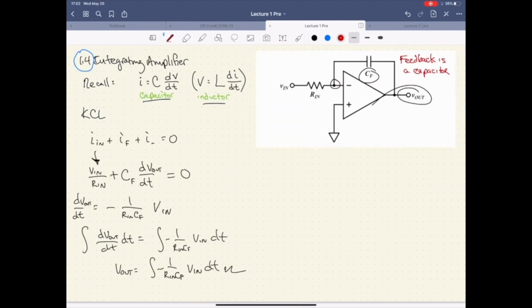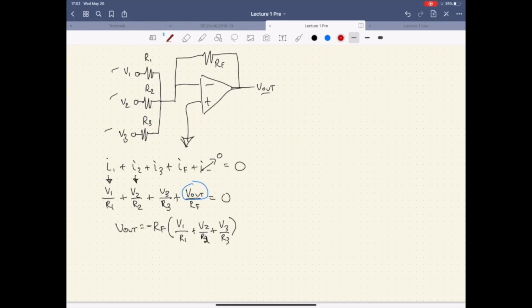And again, with the summing amplifier over here, which we just did, I wanted to make that note because we've sort of been running along with this assumption that all of these guys here are just their input values on those terminals there, and that there's no difference there, right? And that's because we have our ground right here, and these two potentials are roughly equivalent to each other, so we're able to exploit that assumption. Okay,